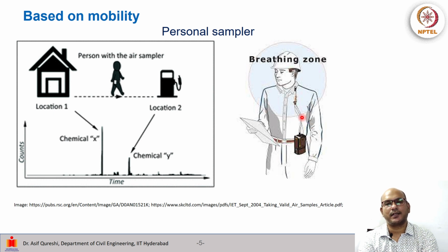So if you are collecting particulate matter, there can be a filter holder and filter here, and this place is open to the air, and the air is sucked through by the pump. So the PM will get filtered on the filter paper in this filter holder, and this PM would be the PM that a person is inhaling every time.